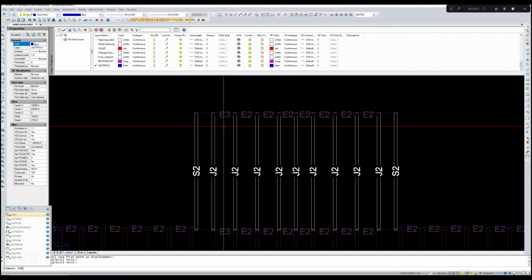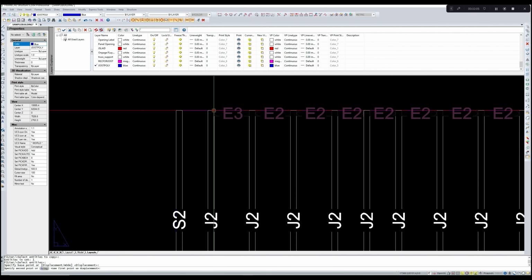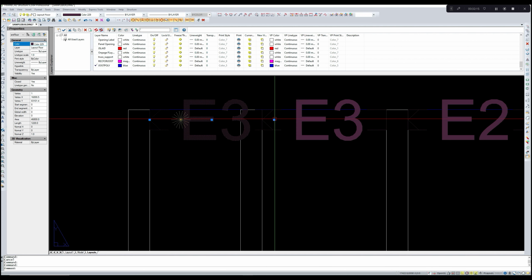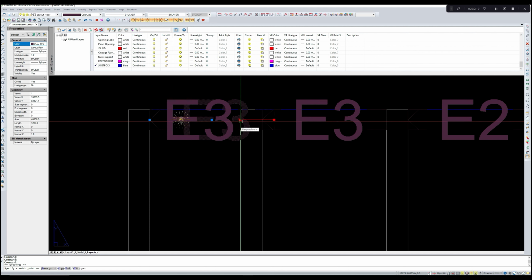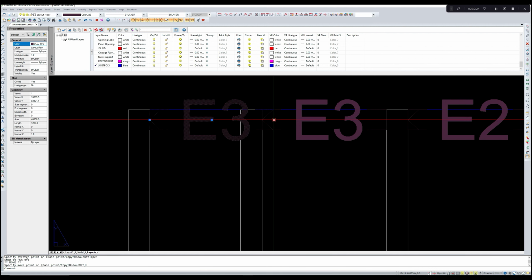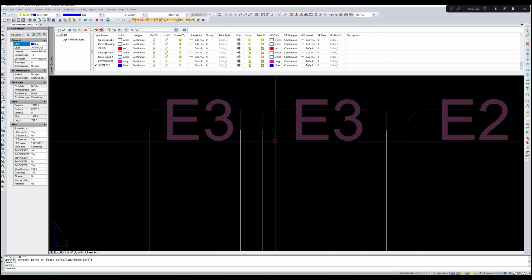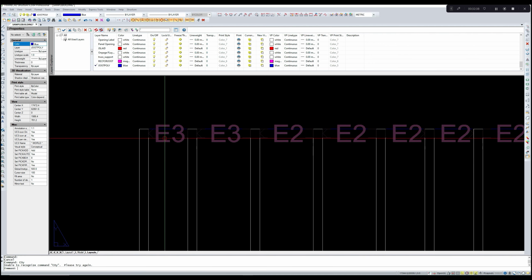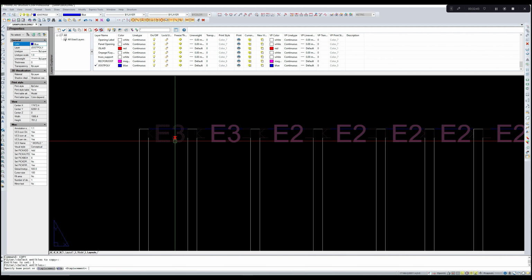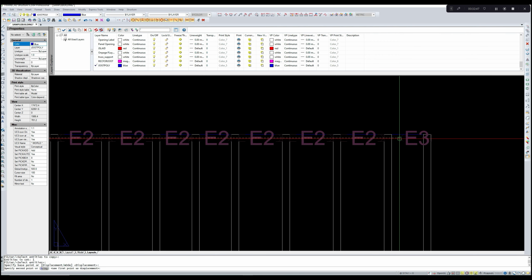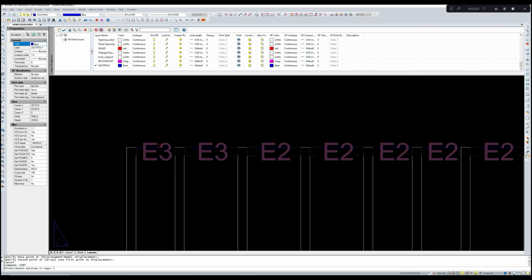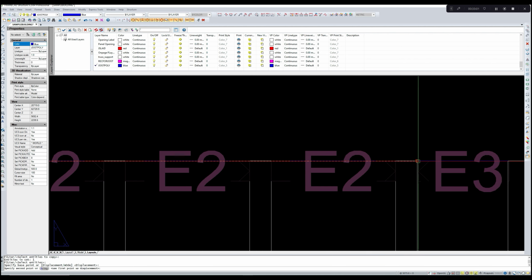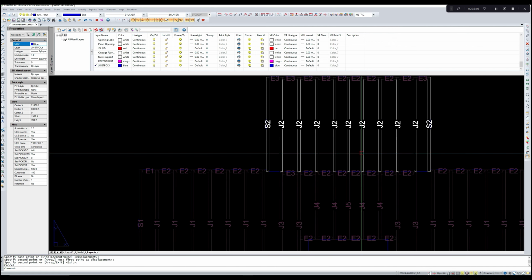Then we have to put an end block at the side as well. Let us take this here. Now click on it, hold the grip point, move it perpendicularly, PER part, enter. Does not move. PER part. Copy this, we copy. See, the end block here seems to be named the same, but when we label it again, the software will automatically label the different blockings with different names. That can be done at a later stage. So two of these parts are complete.